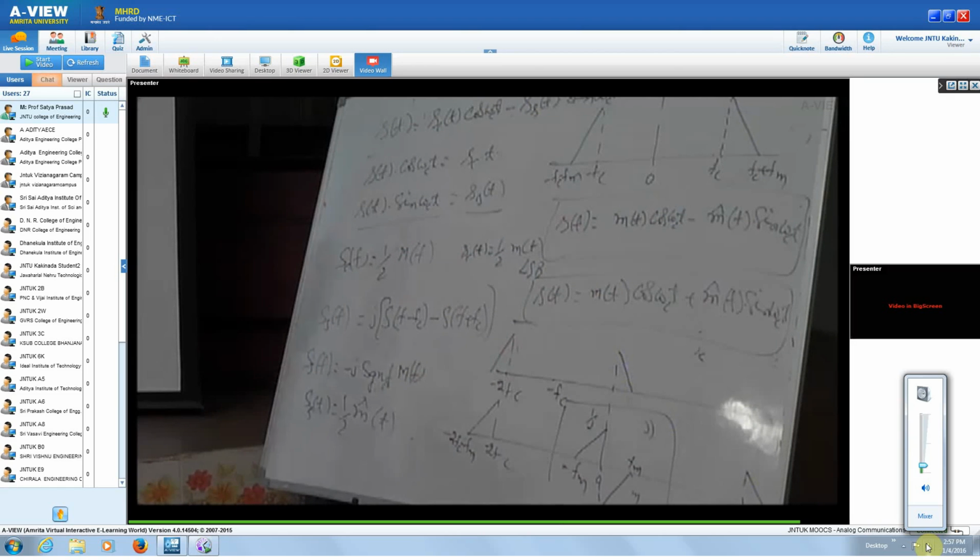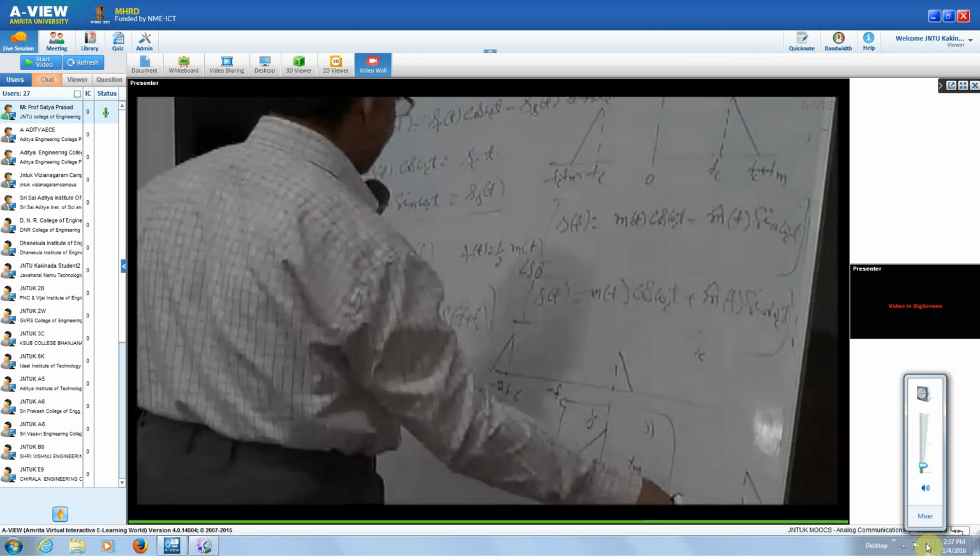And if you are asked for a frequency domain representation, anyhow, a simple spectral domain: FC to FC plus FM, or FC minus FM to FC, along with the negative frequencies also. You have that representation, negative frequencies and positive frequencies. That gives you your frequency domain representation of the SSB signal that we are going to have. How to generate the SSB signal? Because this is what we have got, but we want to generate the signal. So, SSB generation.